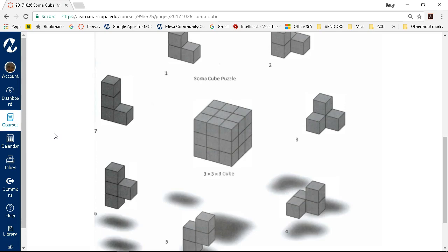We'll start off with the general descriptions, and I think the other videos have probably the good explanation. When we talk about assemblies, we're talking about 6 degrees of freedom. Along each of the axes, X, Y, and Z, we have linear movement, and then rotation about each of those axes gives us 6 degrees. In order for this to be fully defined, fully static, we have to put mate references on all 6 degrees of freedom.